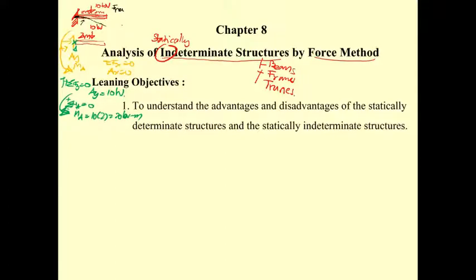Sometimes the balcony of your building may get very large deformation. You can fix this by adding more support to that portion of the balcony. For example, again, you have the balcony like this. The force is still the same, 10 kilonewton. However, this time you may add a support at the free end, and then you may put a column to take care of this.